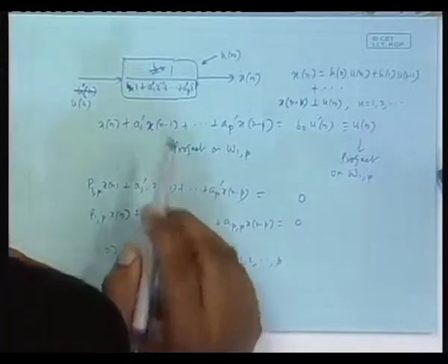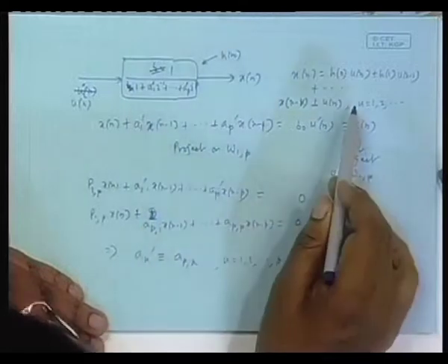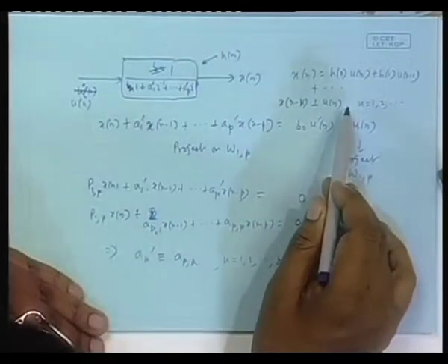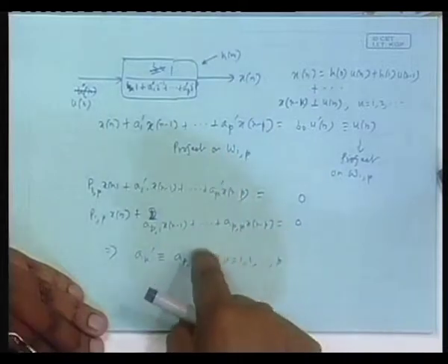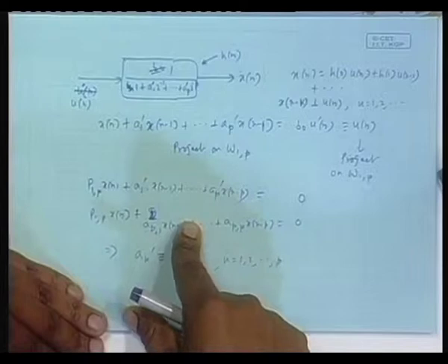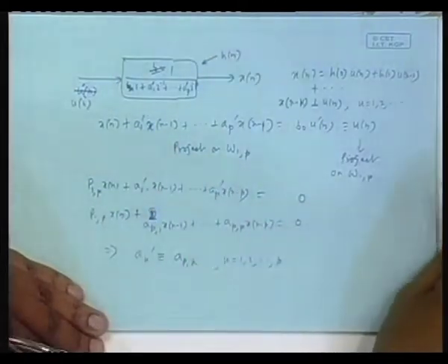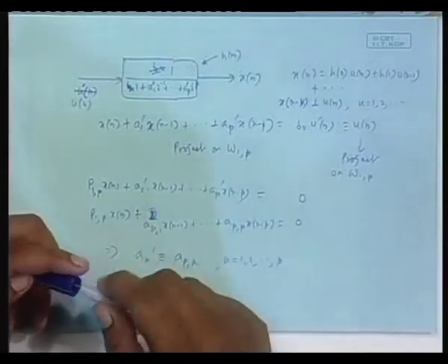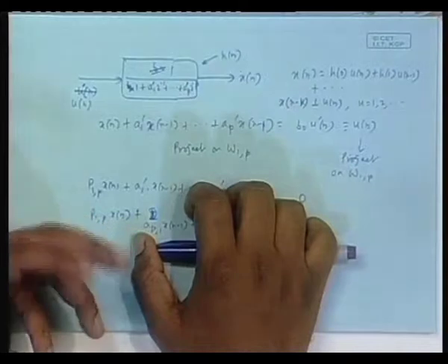Okay. Now, I said that the model must be causal and stable, and that fact I have used here; using that only I got this relation. But how can I justify that this is indeed causal and stable? I proved yesterday that if you do linear prediction, then the linear predictor polynomial is always causal and stable for any order.